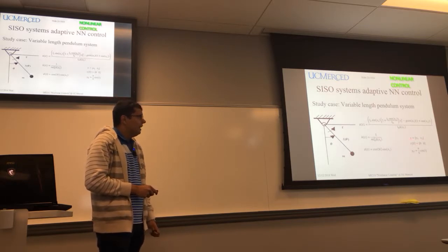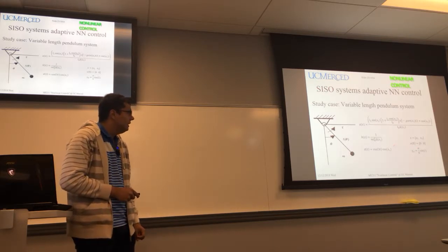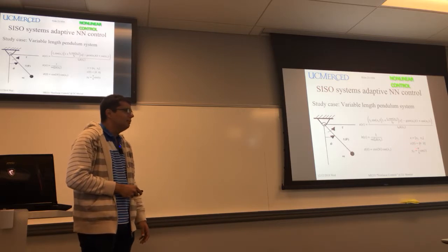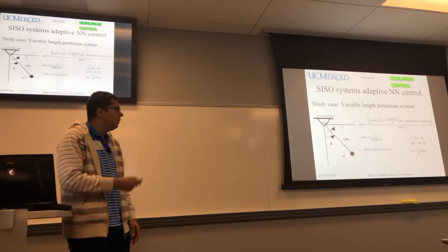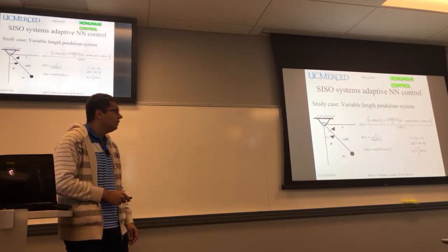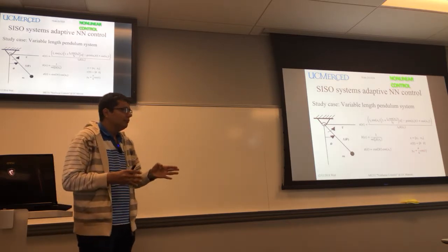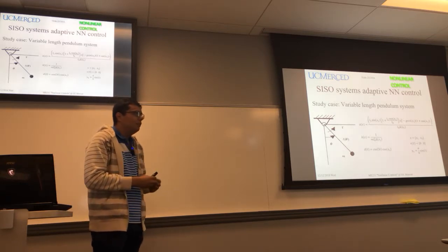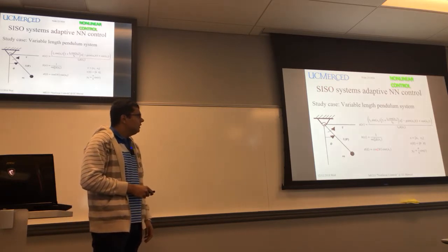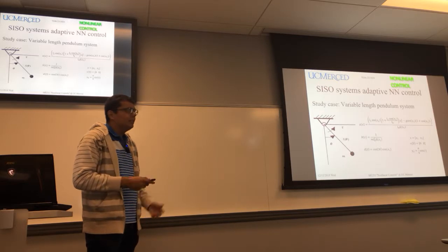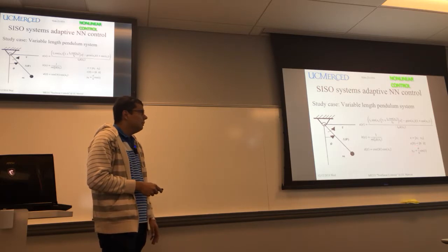Here we have the state vector x1, x2. In this case, x1 and x2 are the position and the velocity of the system. The initial conditions for this system are 0, 0, which is in addition the equilibrium point of our system. This is the desired trajectory that we want the pendulum to follow. This trajectory is bounded because, as we said before, we cannot extend these controllers globally. And we have, in addition, this disturbance that affects the applied torque to the system. So it's a nonlinear system with disturbance, bounded into a range.